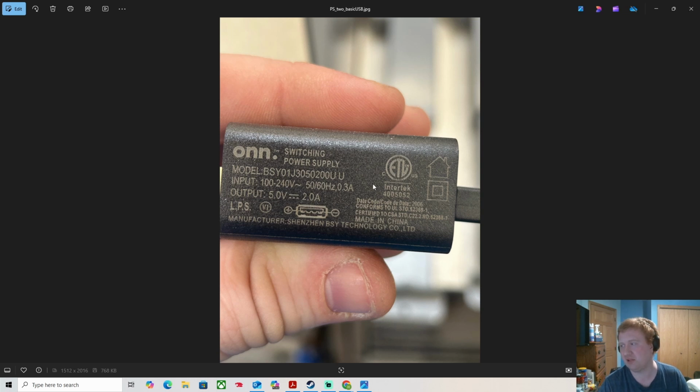That's typically what these end up being, because switch mode power supplies are a lot more efficient than transformer linear supplies. But even 2.1 amps might be too much. It depends on the internals, but basically if the connected circuit or system draws pretty much anything over that, the power supply will burn out almost instantly.